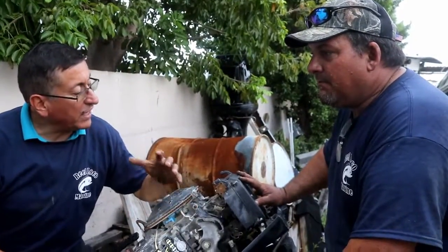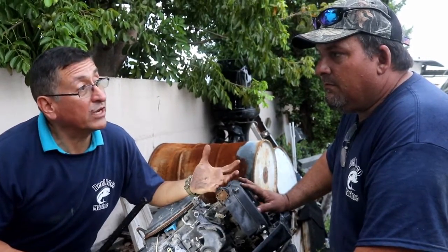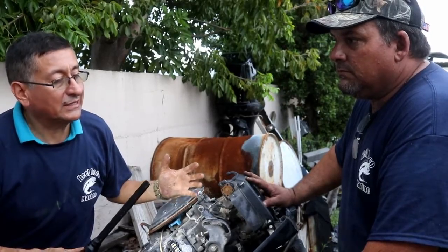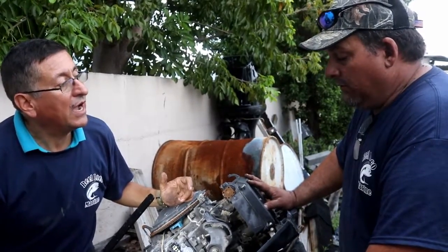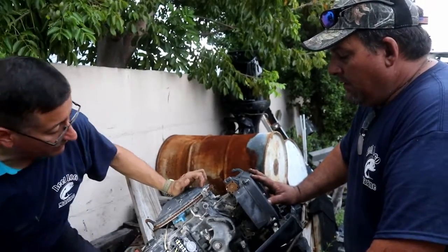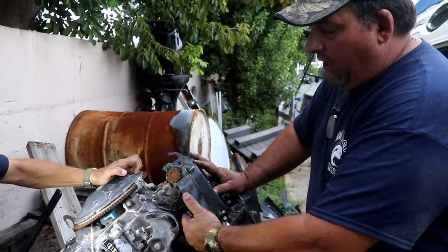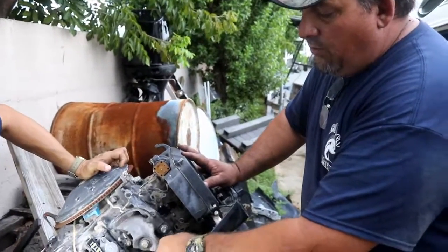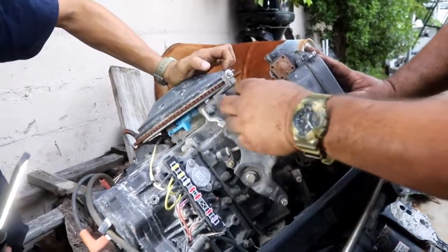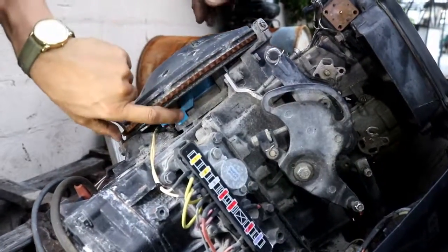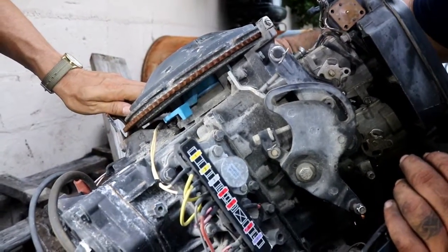Danny, I know that the new modern electronic engines don't need timing adjustment because the computer is intelligent and adjusts the timing. Correct. But in older engines like this, carbureted with mechanical system, the timing adjustment is important. Absolutely. How is the procedure to calibrate the timing here? Well, just like we saw in the previous videos, you have to make sure that all the flaps are closed. Then you have a cam that goes in here. So when you advance the throttle, there's a rod that moves this, and this is what advances or retards your timing.